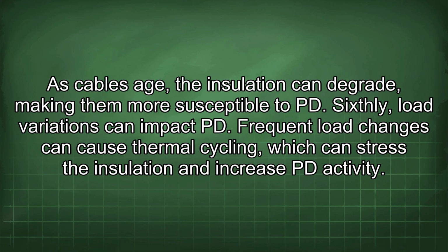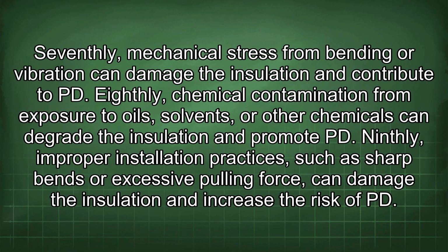Sixthly, load variations can impact PD. Frequent load changes can cause thermal cycling, which can stress the insulation and increase PD activity. Seventhly, mechanical stress from bending or vibration can damage the insulation and contribute to PD. Eighthly, chemical contamination from exposure to oils, solvents, or other chemicals can degrade the insulation and promote PD.